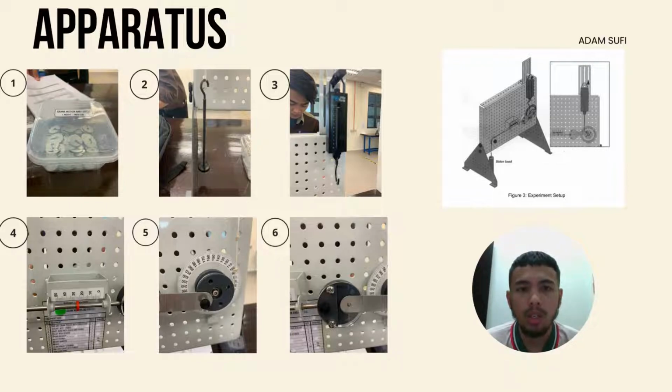Number 4, follower shaft. It is used as a guide roller for cam mechanism or straight motion. Number 5, crank arm with fixing. Used to adjust the slide load on the bearing and holds the arm in place while you tighten up the crank hinge bolt to the proper torque spec. And the last one is shaft guide. It is also used as guide roller for cam mechanism or straight motion. All of the apparatus must be set up as shown on the figure 3.